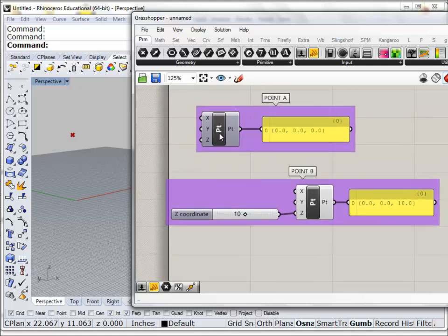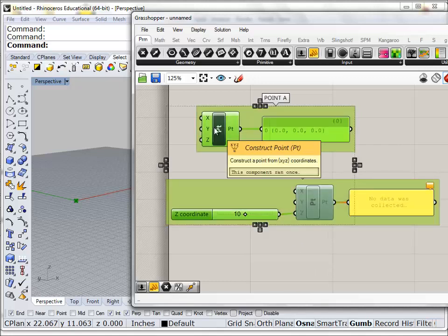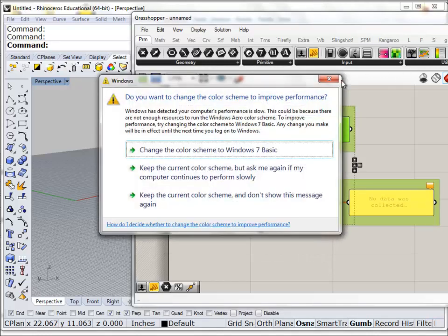The other shortcut that we're going to learn is Control E. When you use Control E, you are able to disable your component. So for preview it is Control Q, for enabling or disabling it is Control E. And it's the same type of on and off option. If one is enabled, it will be disabled, and the opposite.